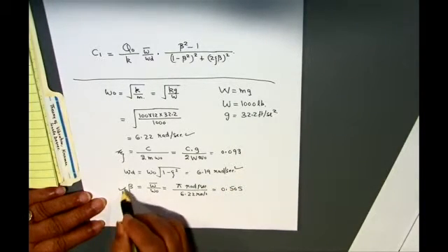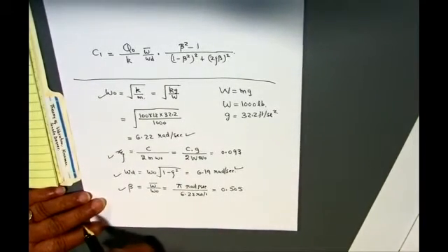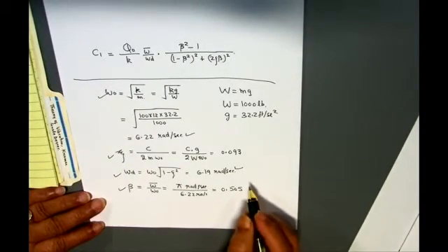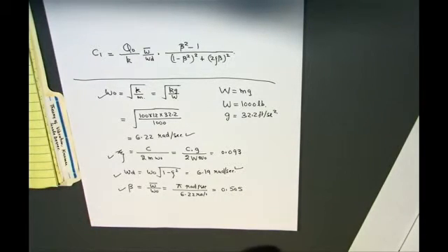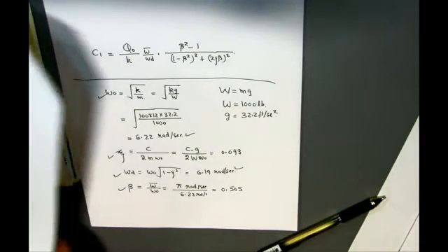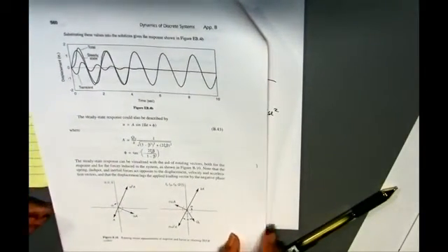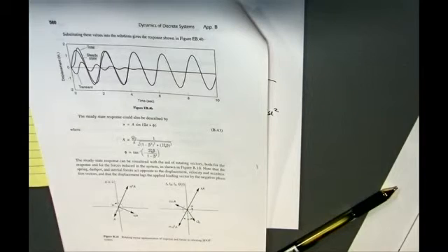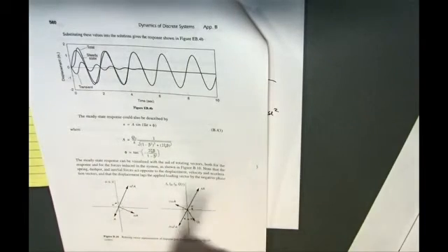Now you know beta, omega d, zeta, omega 0. We already know the value of q, which is 100 pound, and we know omega bar. So we can substitute these values in those equations, and you will get the response something like this. We can get the response which will have decay with time, and you will have a steady state response.